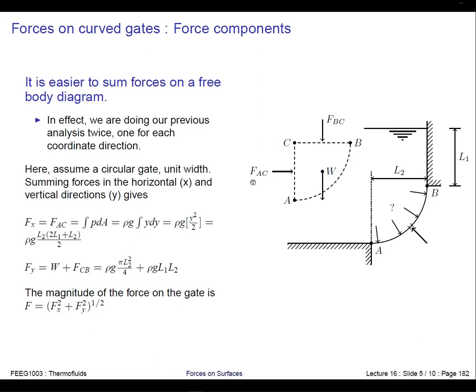Okay, so we've got a force acting in the horizontal direction because we've got a pressure distribution on this surface, because there's a column of fluid above here, and that's going to be balanced by the horizontal component of the resultant force on this curved surface. So there'll be a force on this curved surface that has to balance this thing here. Okay, and there will be forces in a vertical direction.